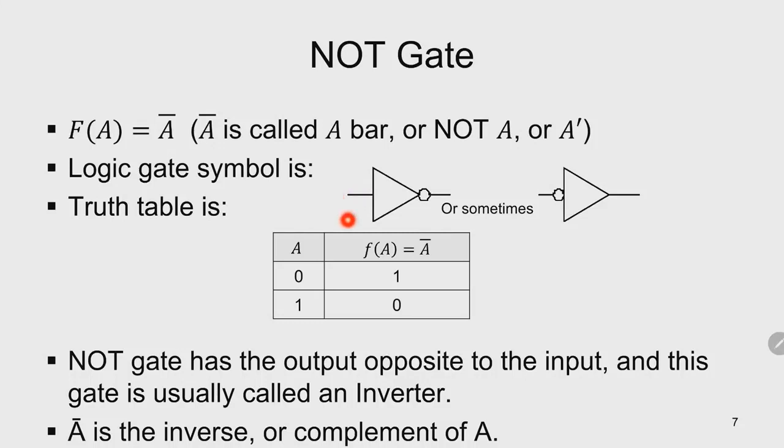So when you power up the inverter and put a multimeter on the input, you measure some voltage at the input, and the output will automatically be low, or 0 voltage. In the other case, the input is active low. When you power up your inverter, there will be no voltage at the input, and if you measure the output, even though you don't put in an input, the output will be high. You get a voltage coming out.